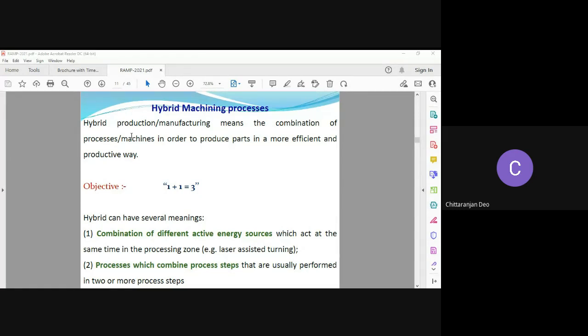To achieve this aim, a hybrid machining process will need to follow at least one of the following principles: within the existing material process window of a process, improving the existing process capability, fulfilling two contrary machining objectives, gaining significant benefit from interaction of different process energies.